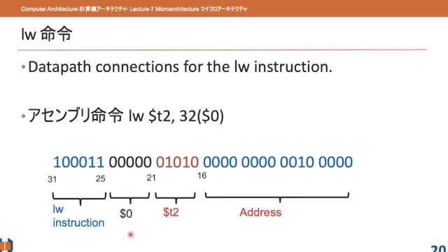As we said, we have two parts, the data path and the control. We need to study these things extensively for every instruction. For example, we pick the load word instruction. The instruction looks like this: load word, temporary register 2, the offset 20, and then register 0. That means we need to load from memory address 20, because this register contains 0. So basically this is the base address, and this is the offset that we studied earlier, and this is the register.